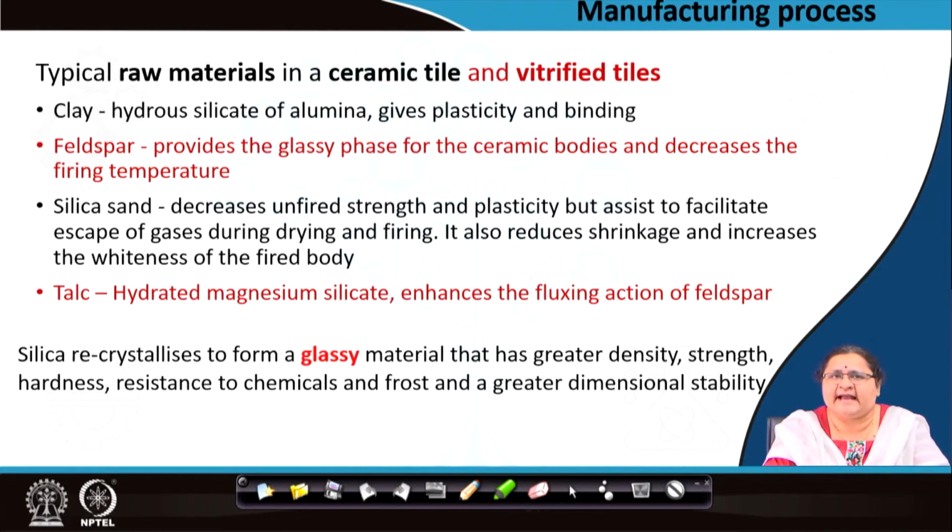and silica sand actually decreases the unfired strength and the plasticity, but facilitates the escape of gases, the fumes which arise due to the reactions when the process is on, when it is in the furnace. It reduces shrinkage and increases the whiteness of the fired body.